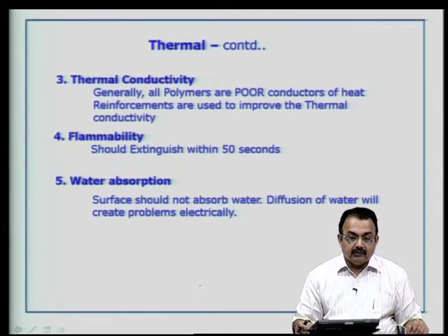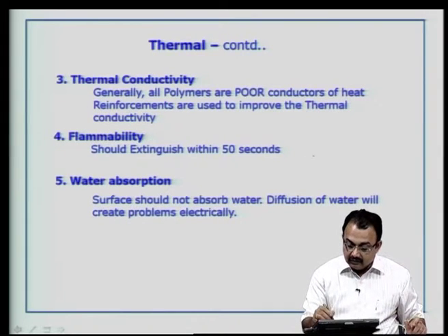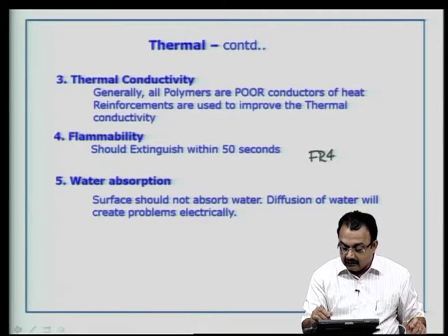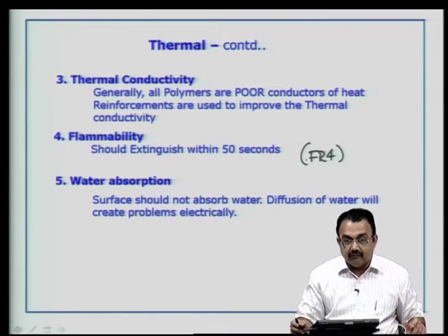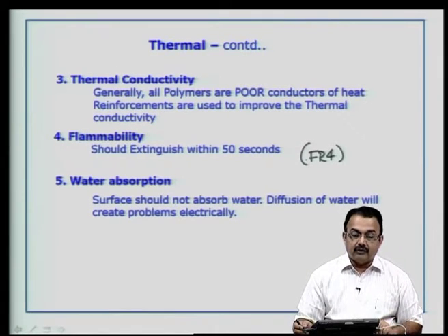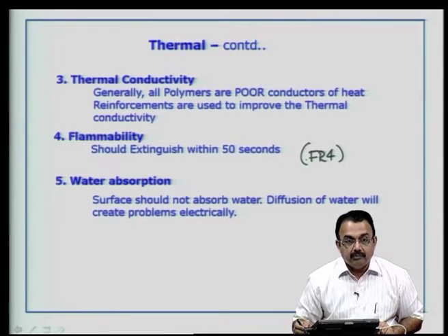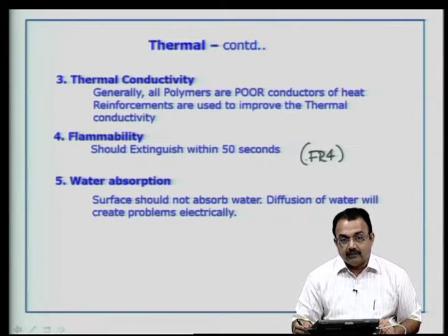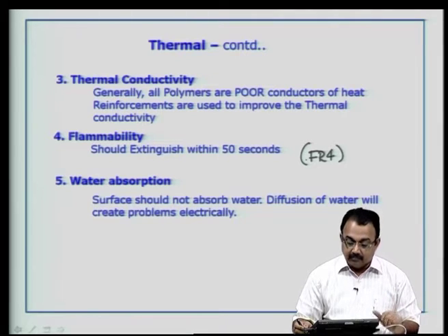Flammability should extinguish within 50 seconds. I was talking about this particular point when we talked about the classification FR4 and so on. So, certain tests are done to find out if it follows this flammability or the self extinguishing property for glass epoxy. Other materials are also available.